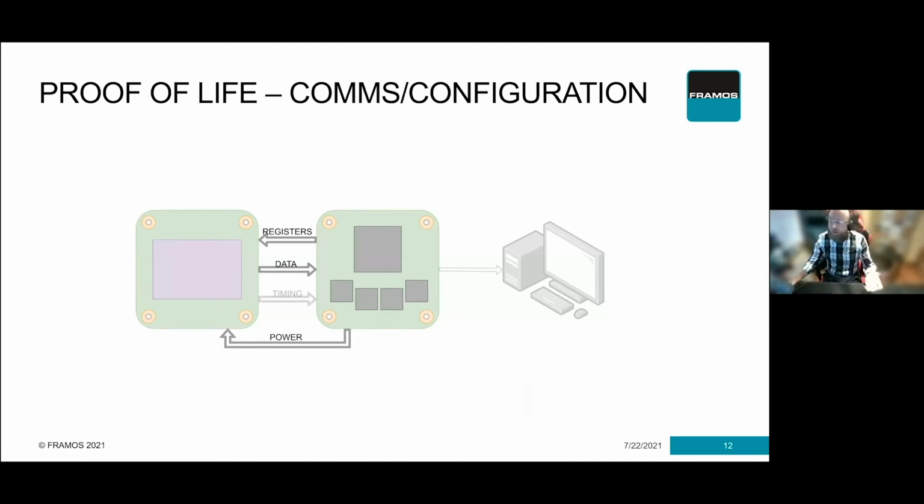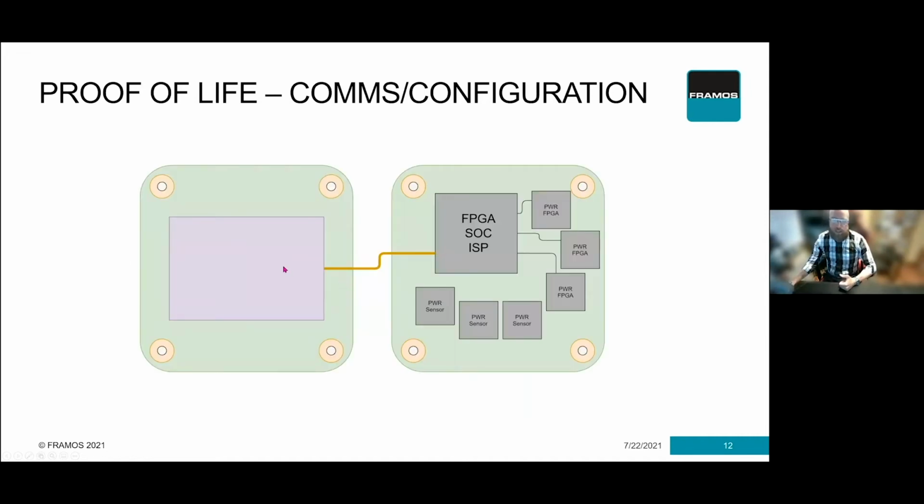Simply saying hello to the address for the image sensor. There's a typical address. Pin strapping, by the way, can also affect that address. You can have multiple different addresses for a particular sensor, so you need to know that your configuration is mapping through to your expected communication. That communication is typically a single little link.